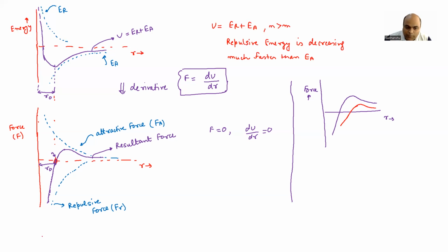So if you see the slope of these two curves, in one case your slope is higher, right? This one. And in another one, so let me mark it here so that you can understand it better. So this is number 1 and this is number 2. Right? So the slope of 1 is higher than the slope of curve 2. What does it mean? It means the stiffness of curve 1 is higher than the stiffness of curve 2. That means in curve 1, the bonds are strongly bonded.